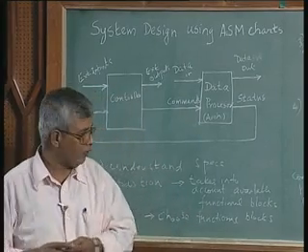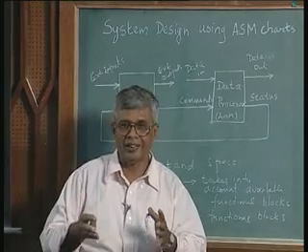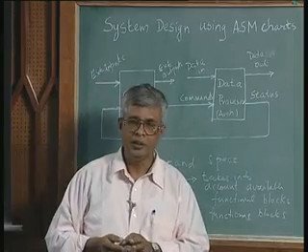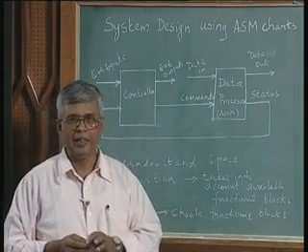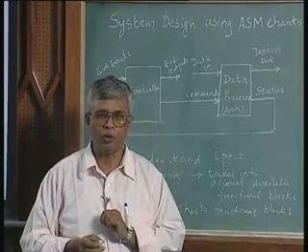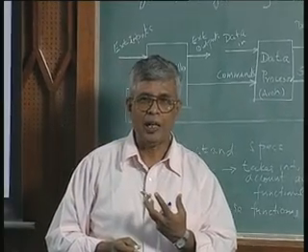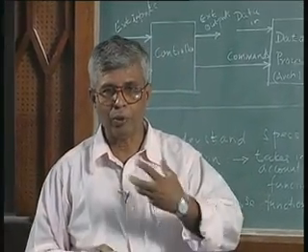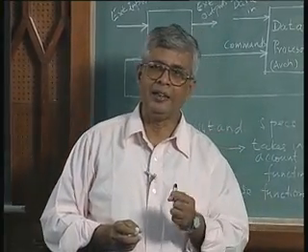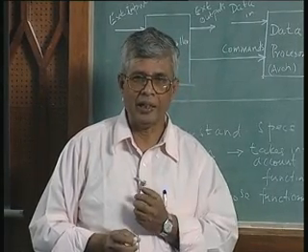because when I say a functional block is off the shelf, it does not mean that you have to go and get it from a shelf. It is a way of saying off the shelf means it is available. In this day of Verilog design and IC design, there are blocks of code available which can be borrowed and inserted. This is called IP, which stands for intellectual property. If you develop a core for a particular function like a multiplier, you can use that again and again whenever that function of multiplication is required. So this is IP based design, they call it core based design.